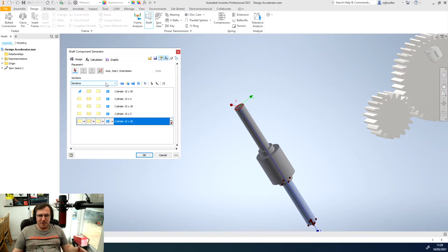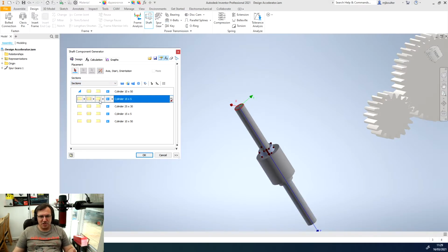So there we have our first shaft. It doesn't look like much, and don't forget as well, if you want to, you can just go back to these and, for instance, on our shelf, our ledge that's going to have the bearing sitting on it, we might want to put a little chamfer at both edges. So distance is 0.5, angle is 45 degrees, and that's going to be fine for what we want.